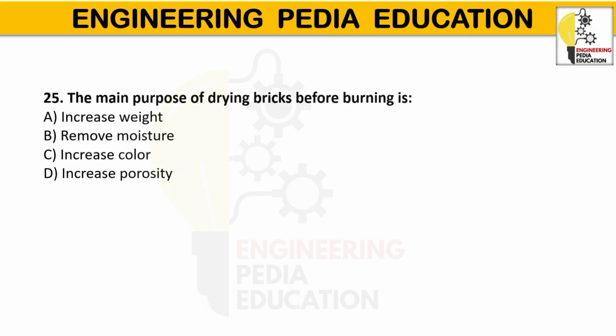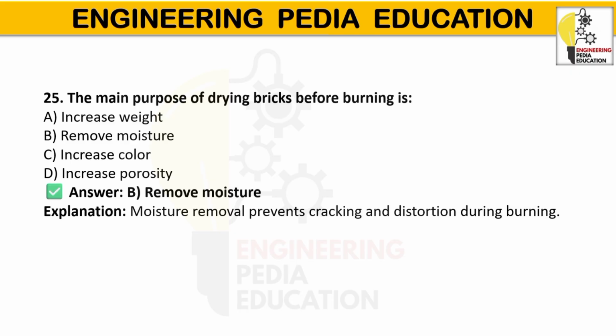The main purpose of drying brick before burning is: increase weight, remove moisture, increase color, increase porosity. So the correct option is remove moisture. Moisture removal prevents cracking and distortion during burning.